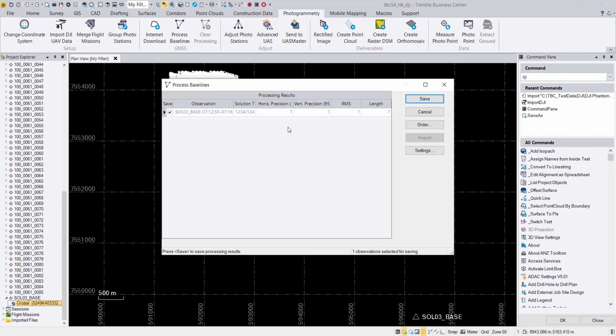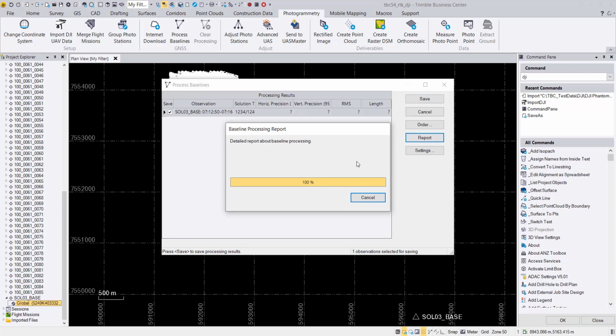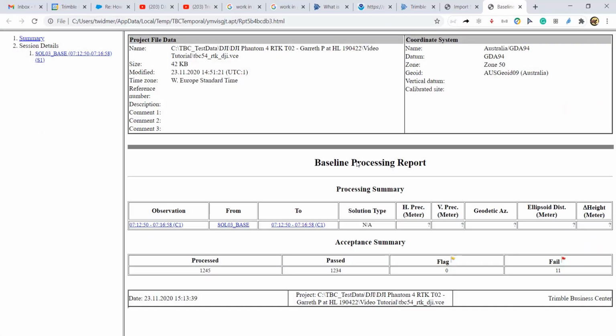It will automatically detect our data, our RINEX data, our, in this case, timestamps data, also our T02 file with the reference station. And then when the solution is done, we can here on the left side click this black arrow, and then the report button should be available. And then when we hit the report button, we can now see the solution that was calculated for our project.